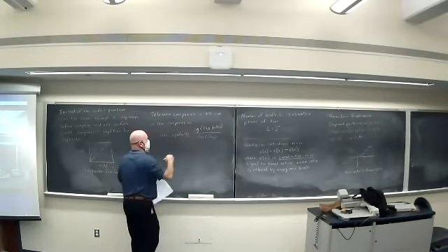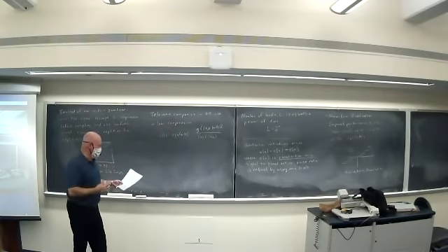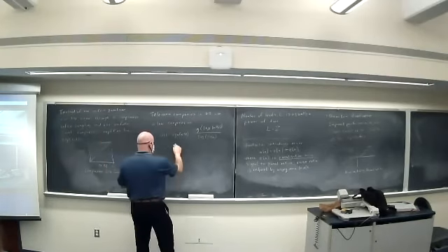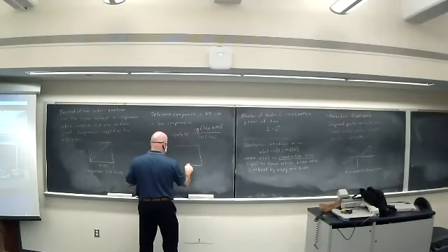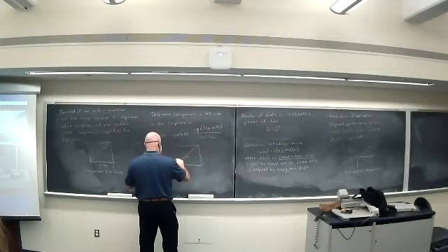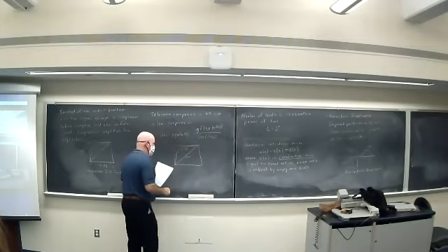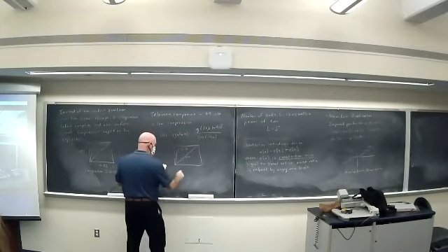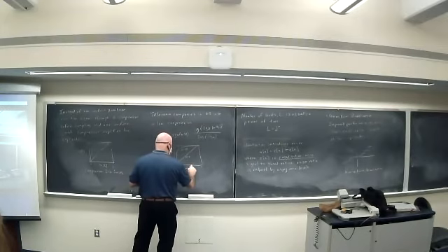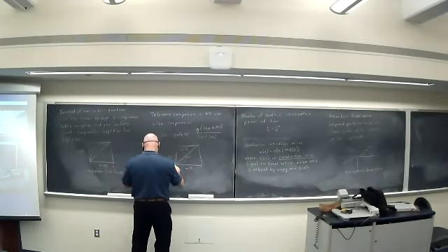The sign just preserves the sign of m. If it's negative, this result is negative. What this curve looks like depends on mu. You get a straight line if mu is equal to 0, and mu equals 255, which is typically used in the US, is going to look like that. This is 0 to 1, m(t) and v(t).